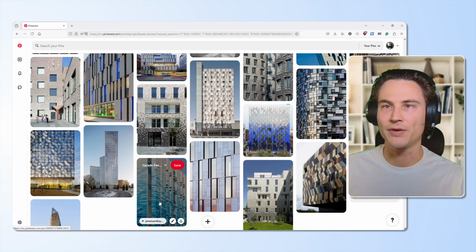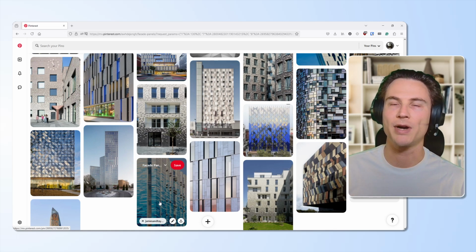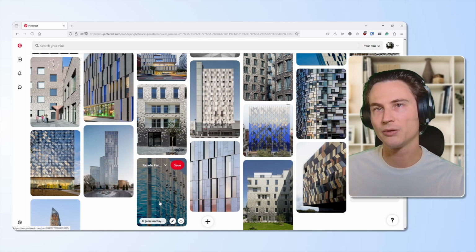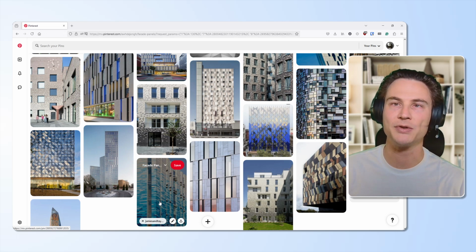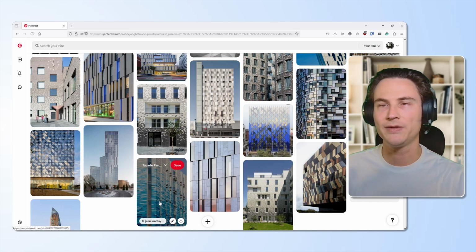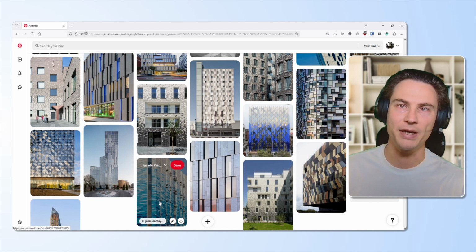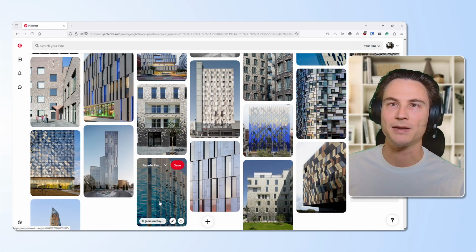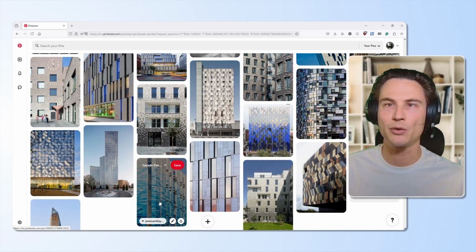There's a new way with Rhino and Grasshopper, with the newest tools in Rhino 8, and we can automate all these tasks. We can attach attributes directly to geometry, like what layer we want to put it on, its material, its color, and a lot of other attributes as well. And we can bake these panels with all their data already included. So this means that if you change one detail, like the size or the color of the panel, everything updates automatically. You press a button and the entire set of facade elements reorganizes itself.